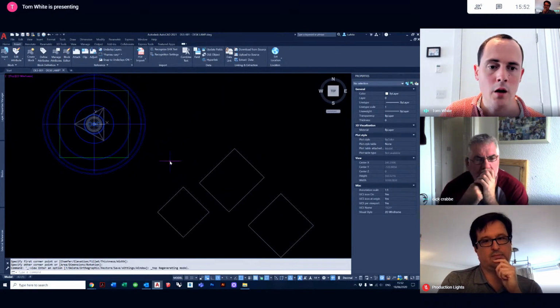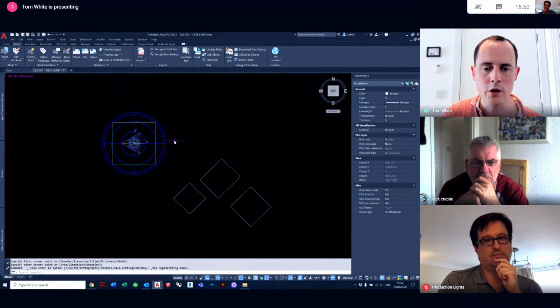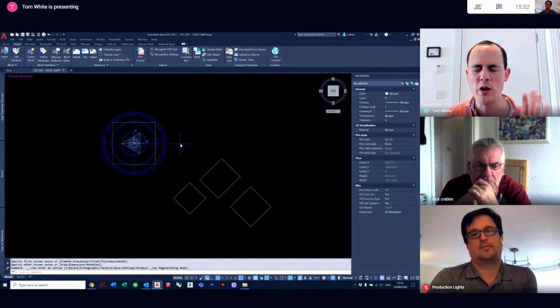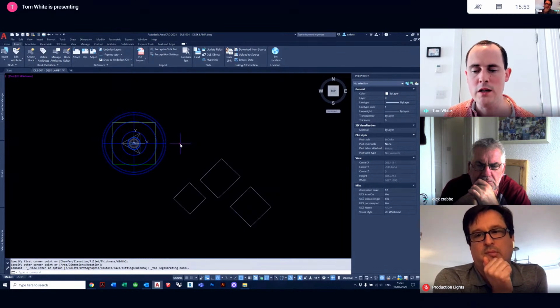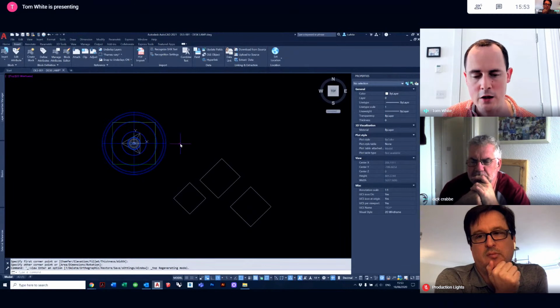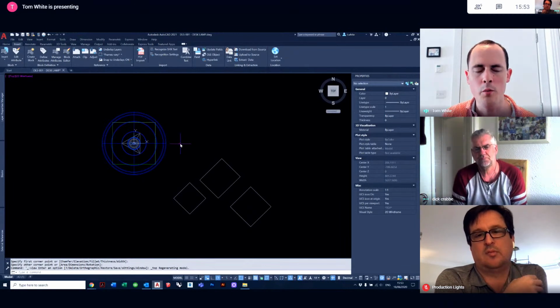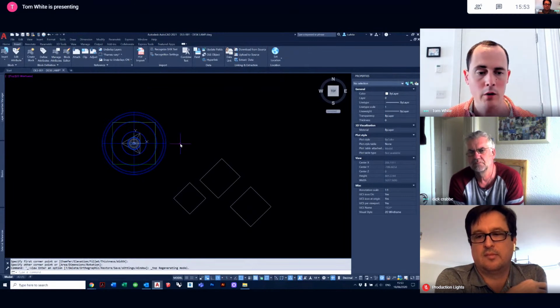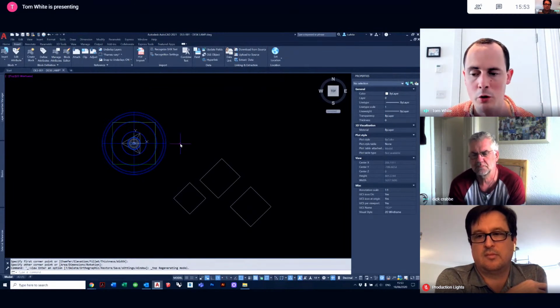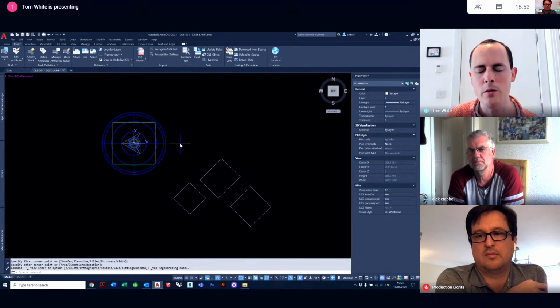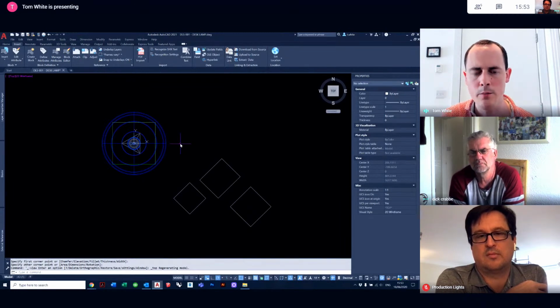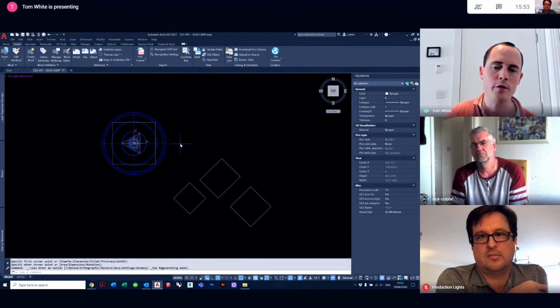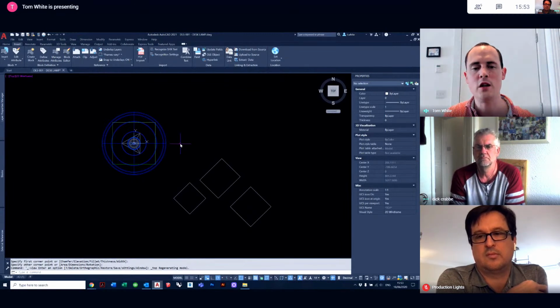A very brilliant thing about World UCS is that two drawings can have World UCS, and ideally, when a project is in its early stages, one person would set the UCS. For example, it might be a known column in the building. If you're working in a theatre, it might be the upstage edge of the fire curtain. But that UCS never changes.